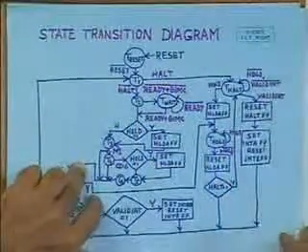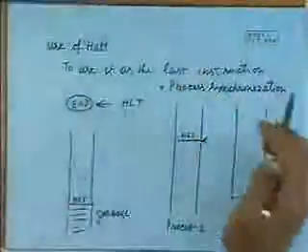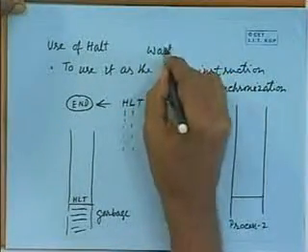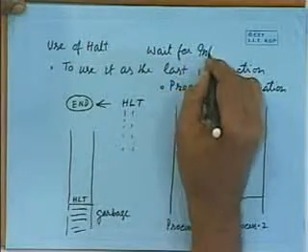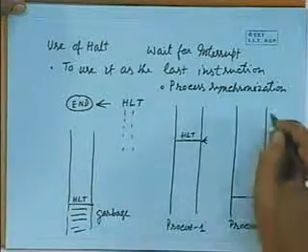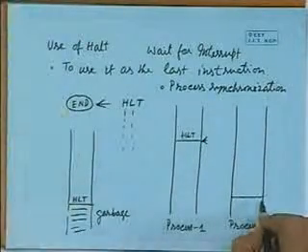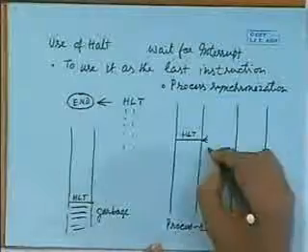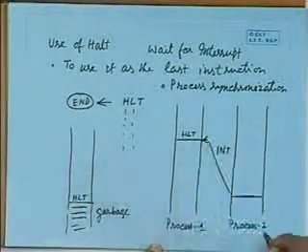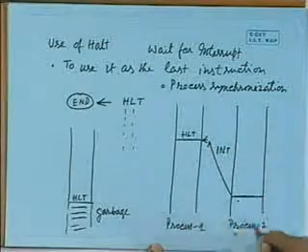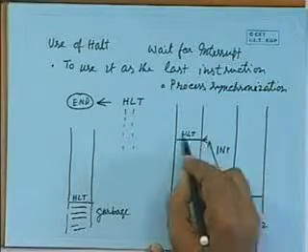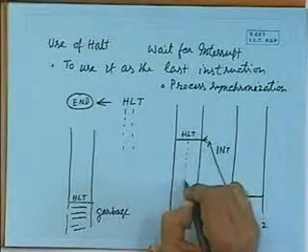That is why this halt is also called wait for interrupt. Now, after reaching this point, processor 2 can generate an interrupt to processor 1. Whenever processor 2 generates an interrupt and it goes to processor 1, it comes out of the halt and starts executing from this point.